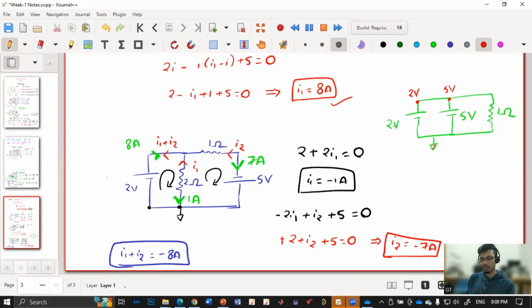In reality, what happens is if I consider a 7 volt battery, and say a 1.5 volt battery, and some 12 volt battery, if I short them, there will be a lot of current flowing. One battery will act like a load, so a lot of current will go into the other battery, and it will be damaged. One of them or both will go off. So I'll tell you how. Say I have connected one battery.